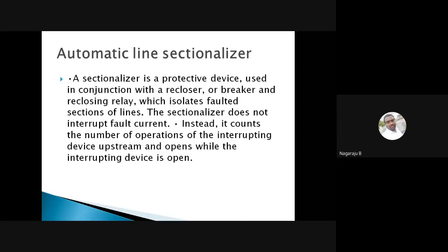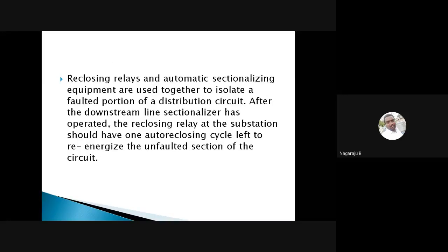Okay, this is about the line sectionalizer. Normally, reclosing relays and automatic sectionalizing equipment are used together to isolate the faulted portion of a distribution circuit.